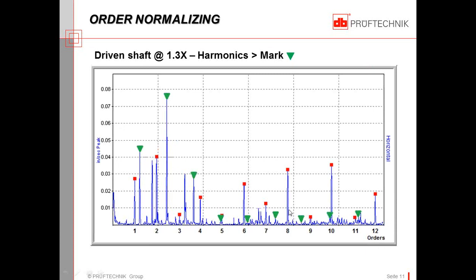And now we're beginning to get a complete picture of this machine vibration. All of the green little deltas are multiples of the load RPM. And are there any other peaks that have not been identified? Apart from these smaller ones down here, we have a couple of significant peaks that are yet to be identified.